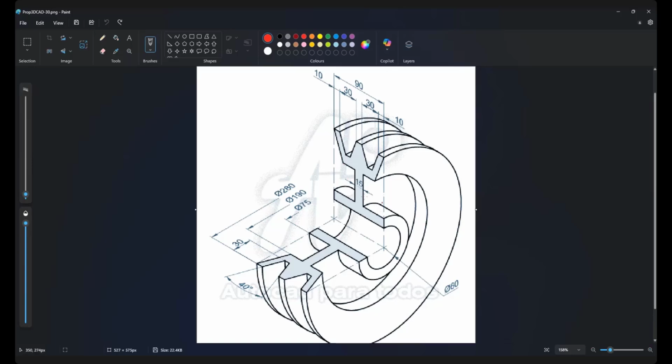Okay, this kind of component, if you look at the shape, is not bounding box modeling. Actually, the idea is that they have a base profile. Then you simply outline the base profile by using a sketch at the appropriate plane in SolidWorks. After you outline and create the base profile, we draw the base profile shape, then we do extrude or revolve.